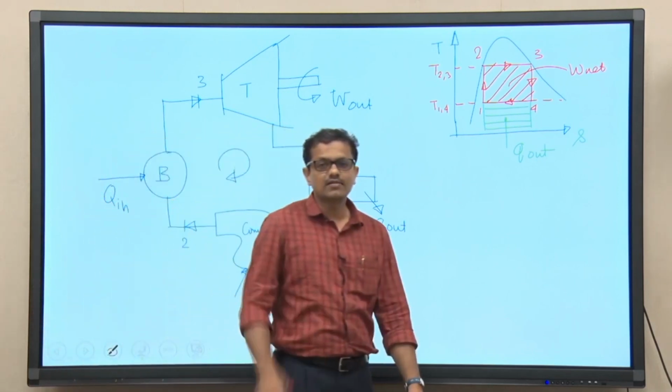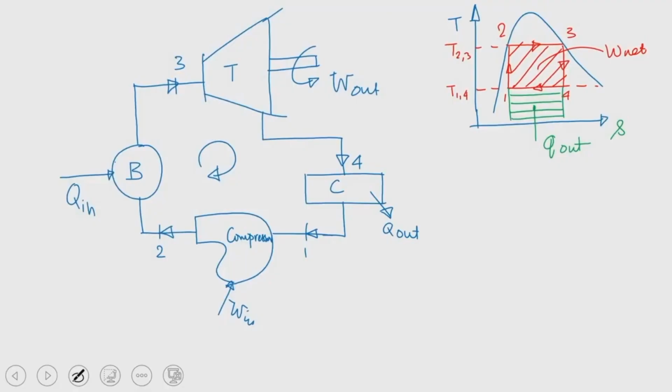We know that for a reversible adiabatic process, T ds equal to dq, so this is equal to 0. So, ds equal to 0. If we integrate from 1 to 2, S2 minus S1 equal to 0, and S2 equal to S1. So, entropy is remaining constant, basically an isentropic process.